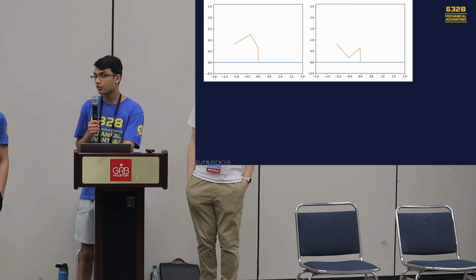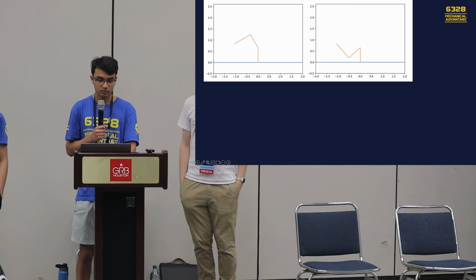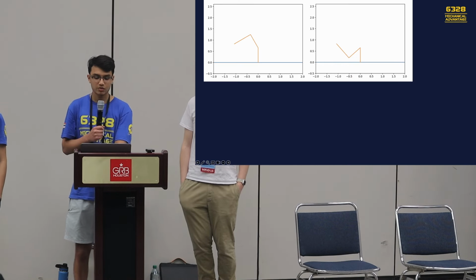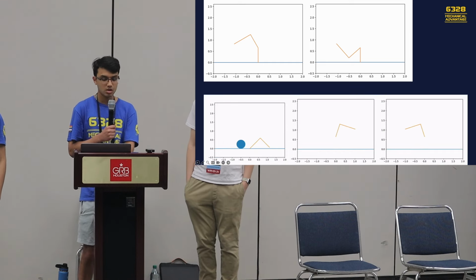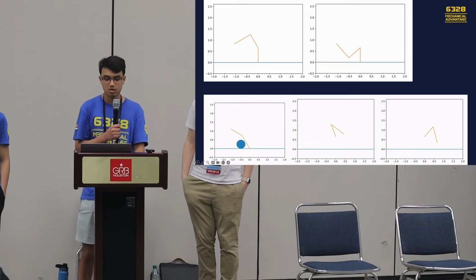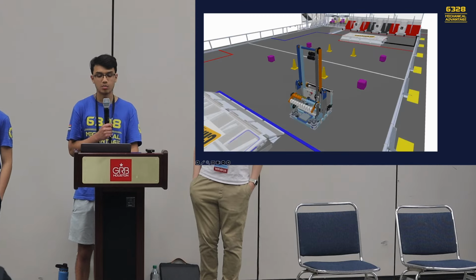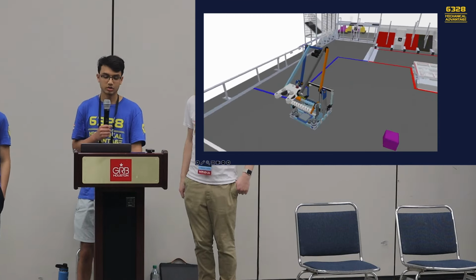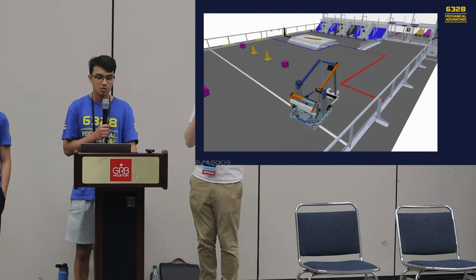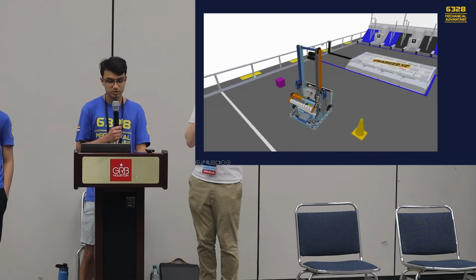Now we got to work writing the code to control this arm. The first step is getting the kinematics right. Throughout this process, we also developed a trajectory generator using numerical optimization. Lots of code development happened here. Remember, all of this was happening before the robot was even ready. So here's what the final simulation looks like. This is it running trajectories with a feed-forward model on PID controllers.